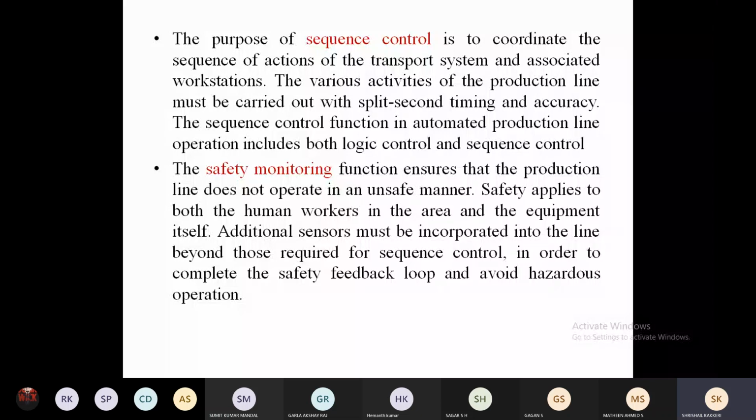The tertiary monitoring system is like a sensor pad provided around the work volume, just like a welcome mat in front of your house. These pads carry sensors. Once any human or object enters, the pads sense its presence and send feedback. Although it is not yet a danger situation, because the intervention is about to happen, a red light or alarm is switched on, meaning some object is entering the system.